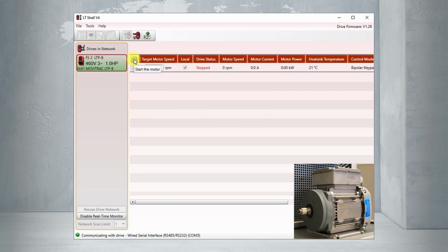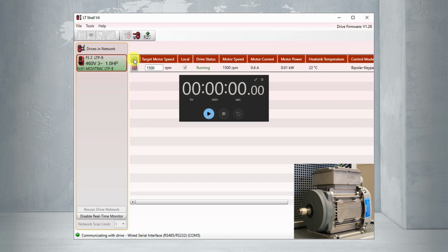Now we're going to test power failure mode. So to do this, we need to re-accelerate our drive, so we'll start it up again. And then what I'm going to do is flip the off switch on my demo unit. That will cause the mains to fail. The VFD should decelerate it quickly using the 1-second rapid stop ramp. And I'm going to actually then turn the power right back on again before the VFD loses complete power. Here we go. So there we go. That obviously took 1 second.